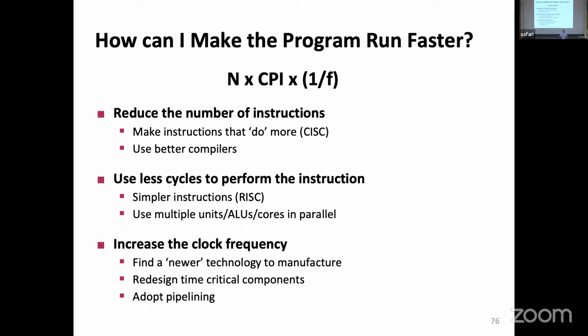We realize that there are some components, like I'm adding numbers all the time. I'm making 32-bit additions. And if you remember, we were talking about the curse of the carry. Guess what? There are so many adders there, and all of the adders are cursed. Like a haunted house, horrible. We can redesign time-critical components, or we can do something that we call pipelining, which seems like a magical thing. That's our topic for next week. We will realize that, hey, we can actually increase the clock frequency without changing the technology and maybe not touching the critical components so much, and everything will be okay.